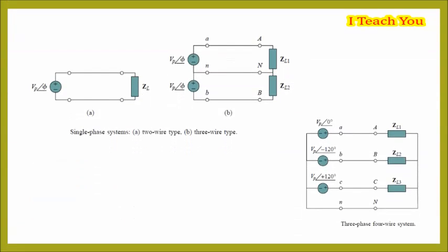The three-phase system has four wires, for example, the three current-carrying conductors and the one neutral. The cross-section area of the neutral conductor is half of the live wire. The current in the neutral wire is equal to the sum of the line currents of the three wires, and consequently equal to square root 3 times the zero-phase sequence components of current.